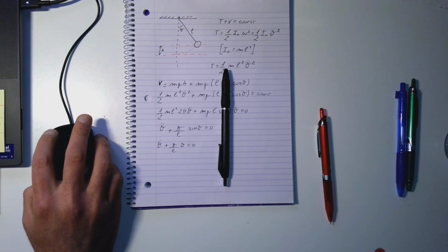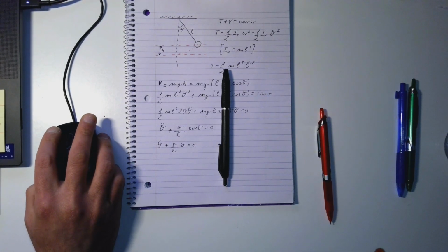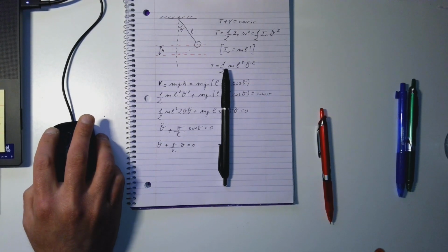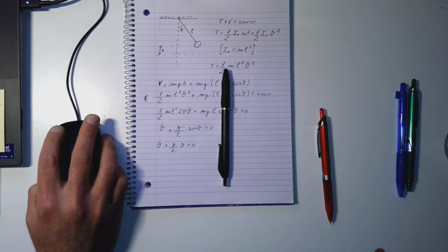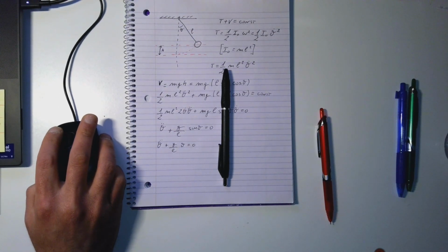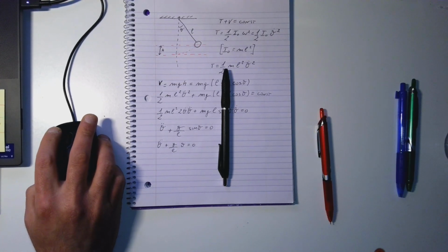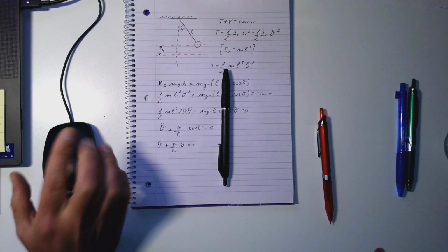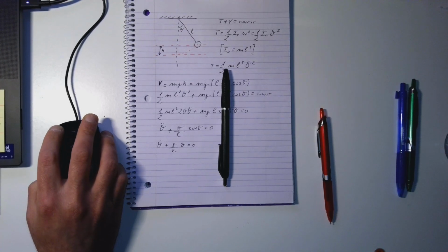The steering rod gear system is modeled as a linear spring and mass system, K2, oscillating in the x direction. The shaft gear mechanism is modeled as the disk of inertia J and torsional stiffness K1. The gear J turns through the angle theta such that the disk does not slip, that's a very important point, on the mass. Obtain the equation in the linear motion x.